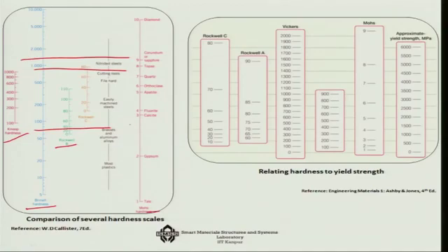The other thing is the formulation that I told you, which is used for the calculation of the yield strength. In this table, from the Ashby and Jones book, you can get the yield strength directly. For example, you get some value like 1200, and you go through this, and you get a yield strength of something like 4000 MPa. So, corresponding to each such value in the hardness testing machine, you can get an approximate yield strength value.